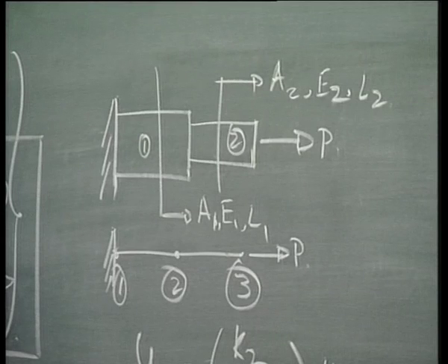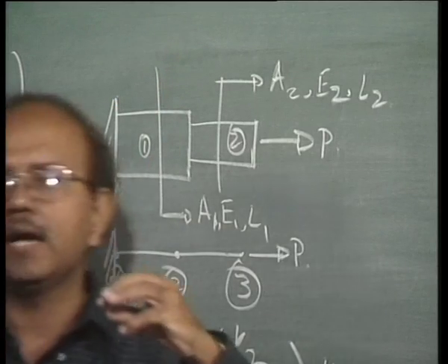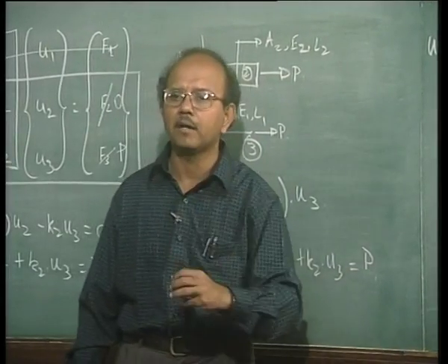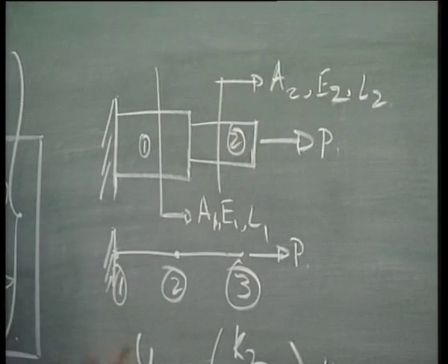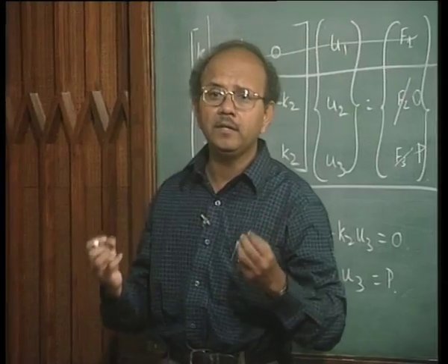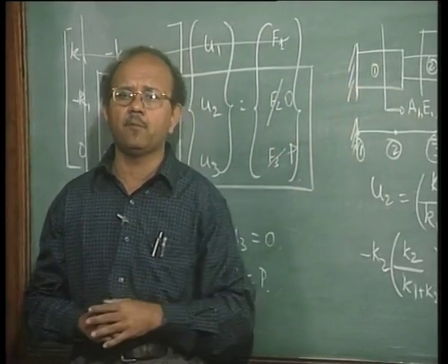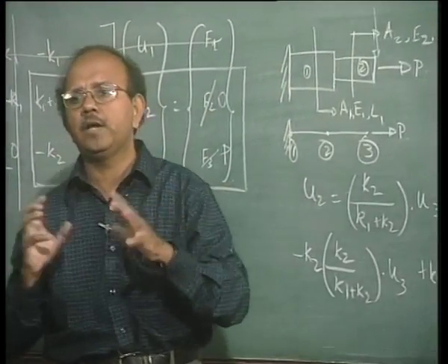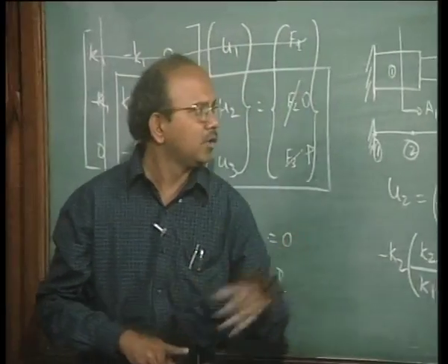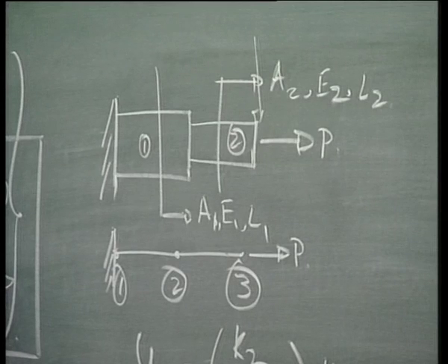Please note there is a difference between geometry and its behavior. The same bar, if I apply another type of load, for example, let us assume that this bar has a circular cross section, and I apply a load in this direction perpendicular to it, what would it undergo? It would undergo bending, correct. So, the behavior of the body would be like a beam. So, the first thing that we did was to immediately recognize from this problem, with the engineering knowledge we have at the back of our mind, that this behavior is a bar behavior.